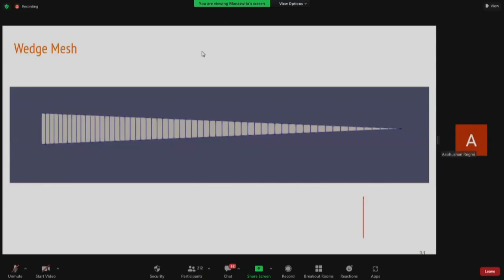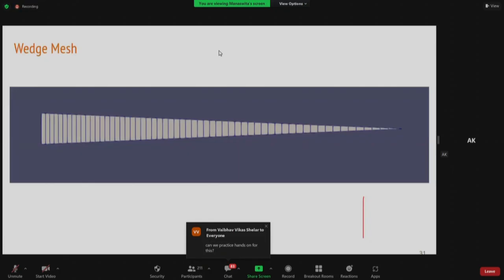Satyanarayan is asking about the boundary condition that you have implemented in the axial direction. Boundary conditions in the axial direction, yes. Also at the wall, no slip at the wall, in radial and axial direction. He's asking, like every phase we have to give the boundary condition. Madam, a follow-up question: this wall effect, is it something people refer to in papers like y plus equal to 1 or something like that? That is for turbulent flow.